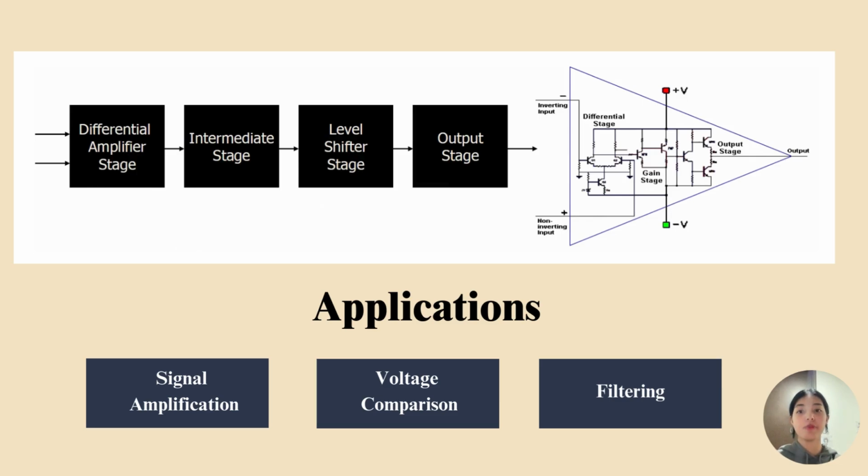An op-amp consists of multiple internal stages that work together to ensure a high gain, good stability, and also signal integrity. I'm going to talk about the four important ones. The first one is the input stage. This stage creates a voltage difference between the inverting and the non-inverting terminals and amplifies that differential signal. As an example, a differential amplifier is used to provide high input impedance, also minimizing signal loading and preserving the integrity of the original input signal.